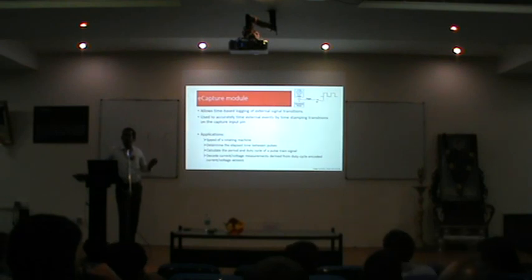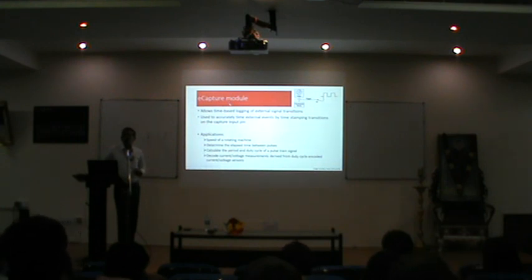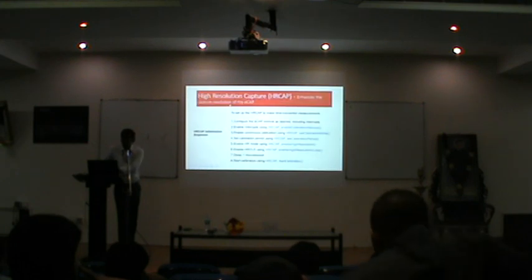Now to do that using a digital controller, what needs to be done? You look into these pulses, you count the number of pulses produced over a period of time, which means that you need a counter which detects these edges and keeps counting. Fortunately, we have functional hardware circuits to do that. Those things are called capture modules. It captures the edges and it increments the counters.